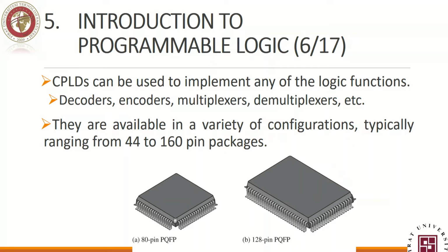As I said, in the first scenario for both PAL and GAL, we expect to implement a limited number of fixed function ICs or certain logic applications, and we do not expect a variety of applications or more complex applications. But for complex PLDs we can accommodate higher level logic functions. What does it mean? Higher level logic functions include decoders, encoders, multiplexers, maybe even memory. So it is for more complicated applications.